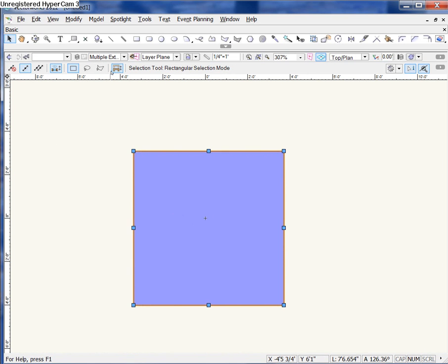Again, top plan, paste back in my original guy here. What happens if I want my original ramp, my just one-sided ramp, but I want it coming up to an edge here? I don't want it to come to a single point, but I also don't want that little landing that I had with my first example. So I can grab the line tool, and I should have no problem drawing a line across here and using that as a multiple extrude, except there is one little catch here.